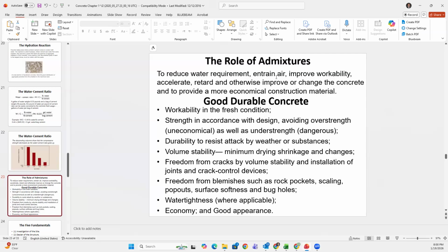I'm serious. If you add chemicals like soap into your concrete, it creates small bubbles in the concrete. That's called air entrainment. After concrete is hard, those bubbles stay in the concrete. Am I clear? So why would you want those small bubbles in concrete? Because your concrete becomes lightweight, because your concrete becomes porous, so it lets the water through it, and because aggregates don't rub against each other. In a cold climate, that concrete expands and contracts without cracking.